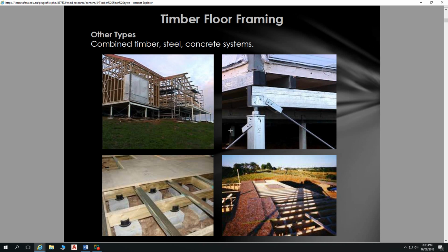In many instances, about half the cost of doing a concrete slab. And certainly where you've got sloping sites like this, you minimise the disturbance to the site, so you're not cutting and filling, you're not building retaining walls, you're not having to divert moisture to the same extent, and you're out of the ground much quicker.